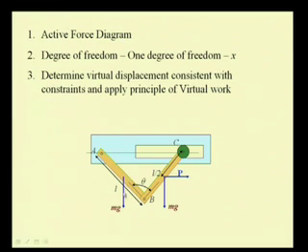It is the self weight of these links, that is mg, the weight of this link AB and the weight of this link BC, which are acting through their center of mass, which is nothing but at a distance of L by 2 from say point A along this link AB, and same way it is L by 2 along this link BC from this point C. And we have this applied force P, which is acting through the center of gravity of this link CB.